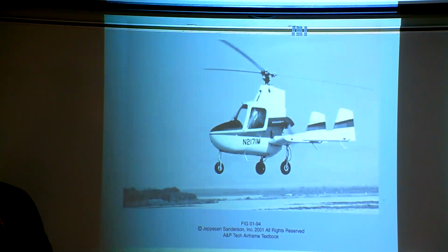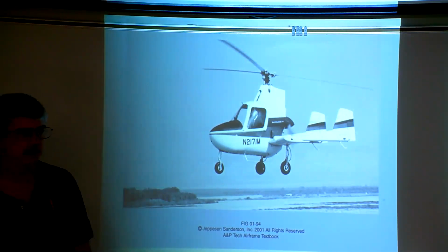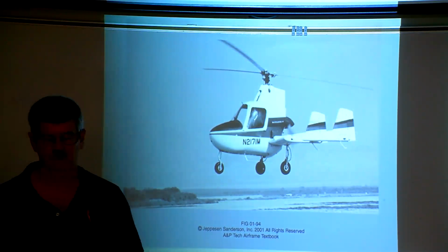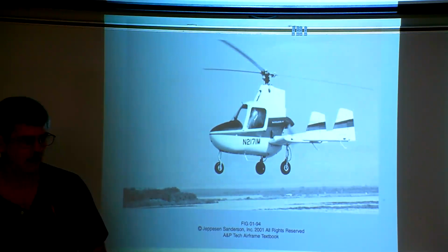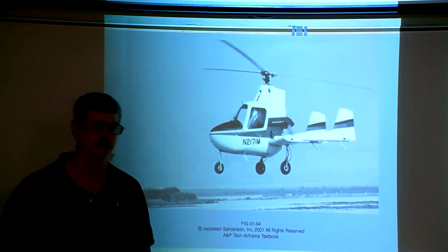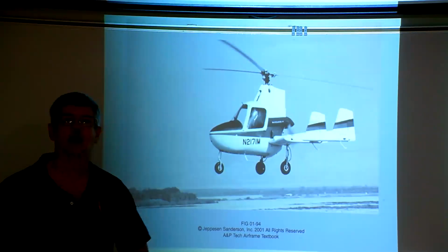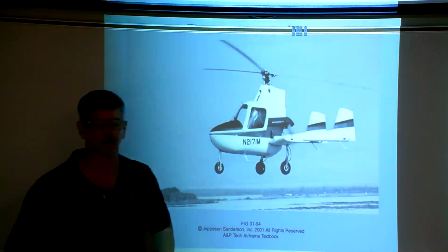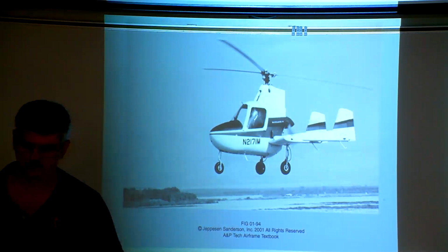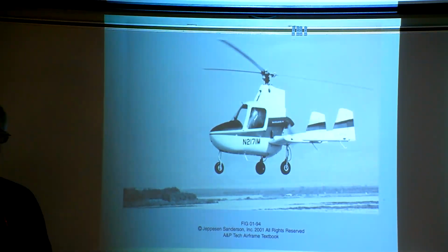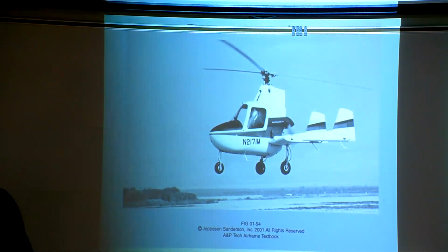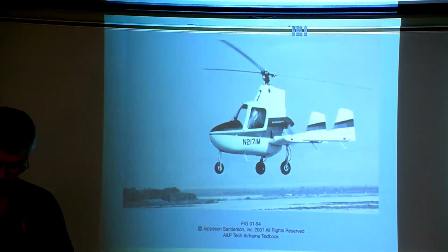The autogyro may have a pitchable rotor, or a tiltable rotor, or the rotor blades can be pitched, or as this one has, it could actually have conventional control surfaces such as ailerons, rudders, and an elevator. Most autogyros do have a rudder though, okay? Even if they don't have ailerons or elevators.